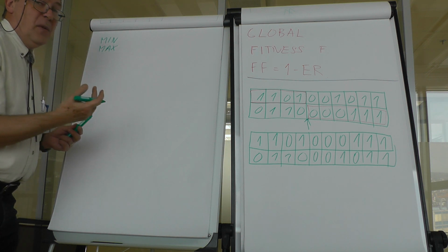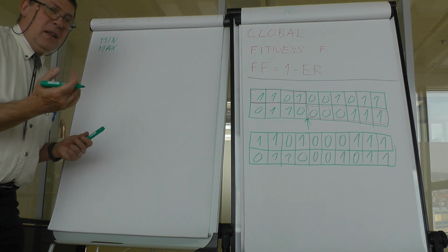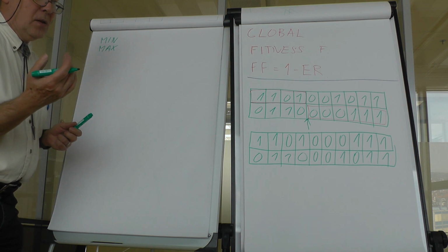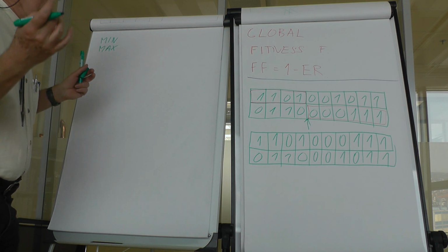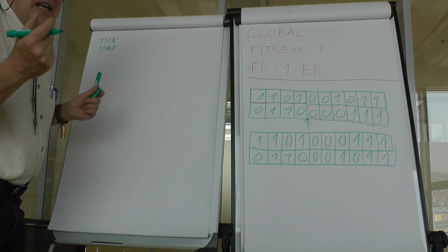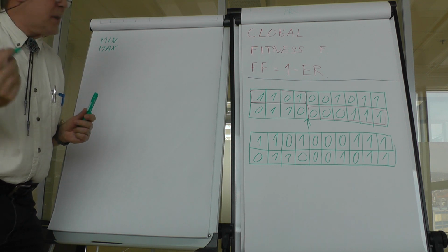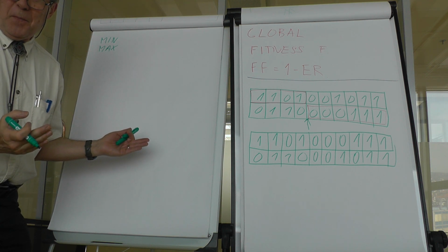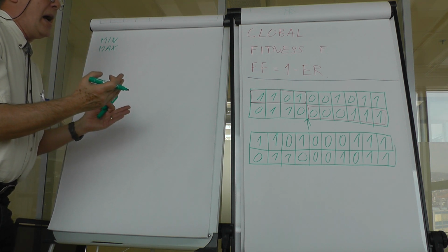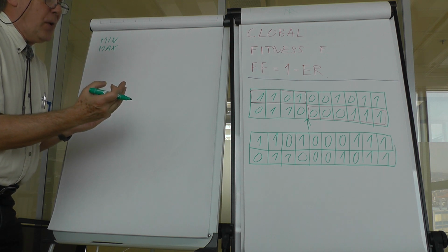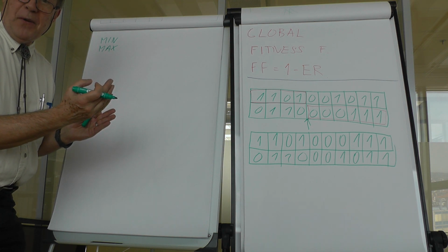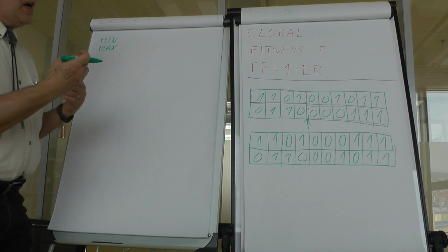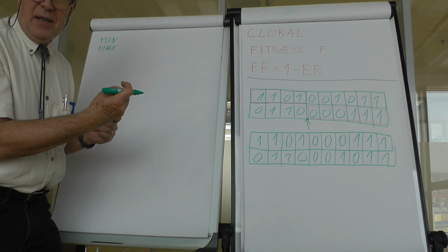And for good dielectrics with low loss factor, I can go up to 10 microfarads, not more. So we will have a minimum and maximum for the capacitor value anyway. And now, within this, I would like to find the proper value. So I will start with a rough estimation.